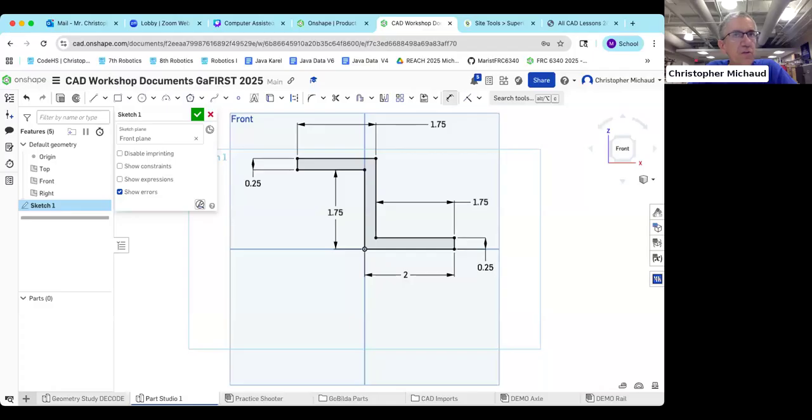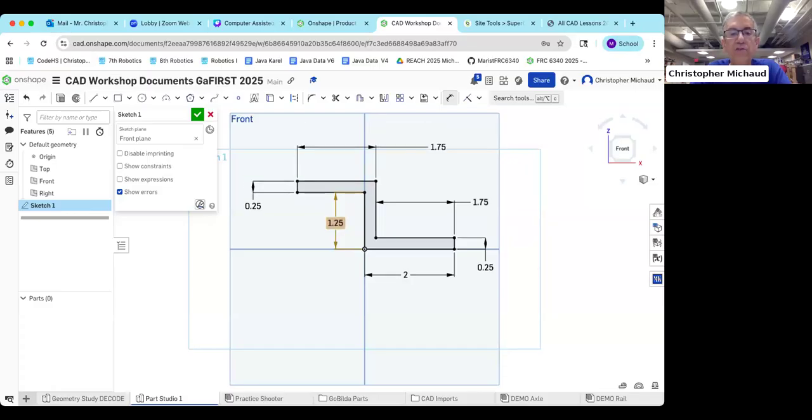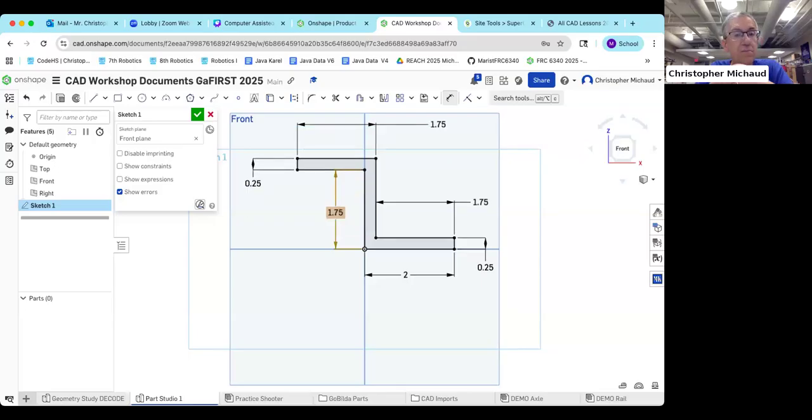For my students, I like to show them this, the first idea, to get the sense that when we're trying to design with some level of precision. The nice thing is, once you set these sizes, if you decide you want it different, let's say you're refining your design and it needs to be 1.25, you can type that and it will resize and repull the shape. And this is where, for prototyping, it works out really well, because you can change your sizes as you're moving along.